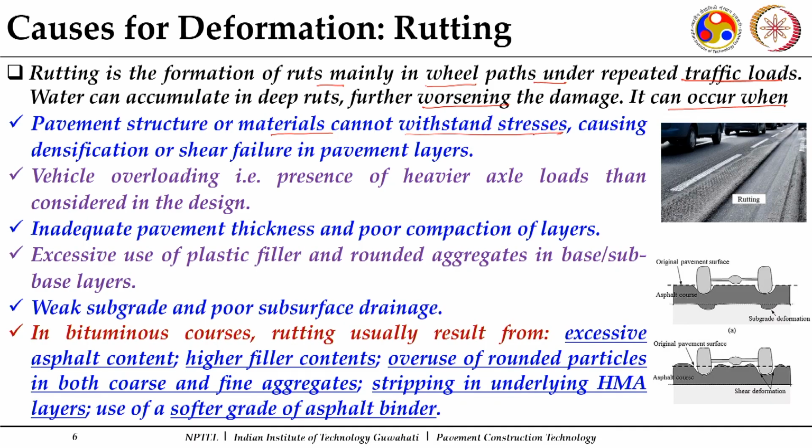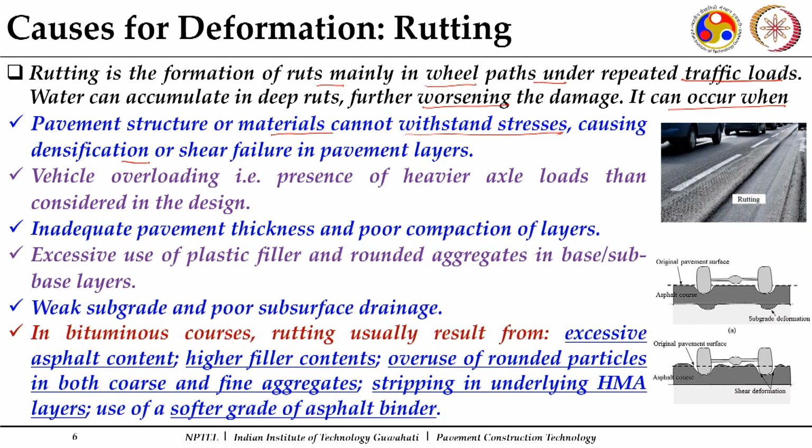We design these layers considering a given strength. If the materials are not meeting those strength requirements that were taken during the design of the crust, then they get overstressed, causing densification or shear failure in the pavement layers.